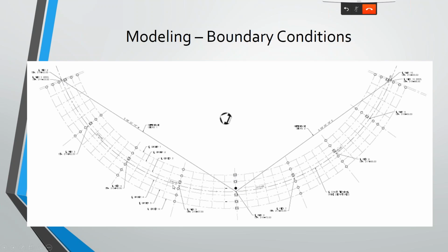So girder line 3 was our controlling girder line. You can see that transversely, we have put in retainers on either side. These are steel retainers to keep that in line with where we want it to go. We did allow some delta, I believe it's about a half inch, between the girder set and actually engaging the retainer. You can do this a number of different ways, which I'll get to in a moment. But these are essentially fixed transversely and free longitudinally. These are all free, so this is going to be the controlling, and these generally just float from here.